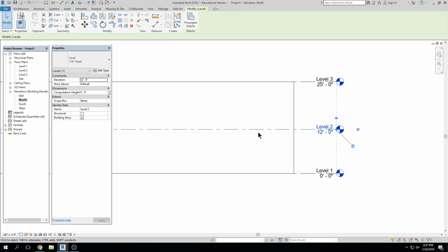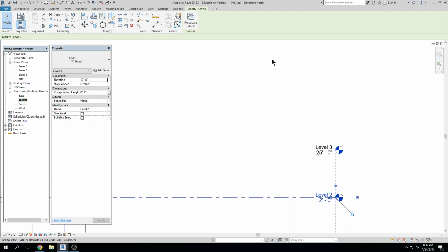Floor joists if there's a second level, or roof joists or whatever. So we'll have maybe the top of the wall, and then we'll have a space where we have joists, and then the top of the joist is really going to be the top of the second level floor. And then potentially we could have another level that goes up to a certain point, and then we have another roof structure, whether it's trusses or joists or whatever. And then above that we have a roof.